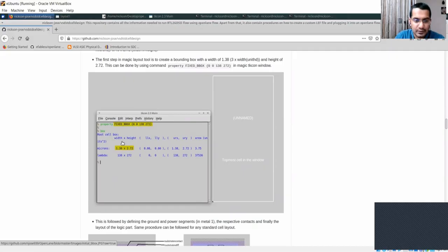You deposit again a layer of Si3N4 or SiO2. So it could be anything. Basically, Si3N4 is the one which is used to protect the chip. So assuming this is the last level of your chip, this is where your interconnects come out. We'll use the Si3N4, which is a stronger dielectric, to protect the bottom layers from the top. So this will actually protect your chip. This acts as your protection layer for your entire chip.